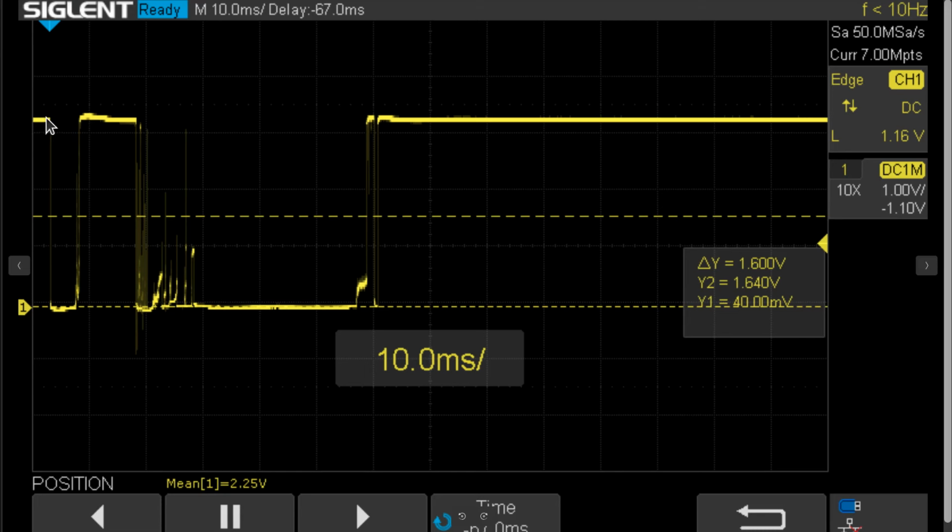So in this case, it would go from a 1 to a 0, and as long as it stays 0 for max count number of clock ticks, and remember, I'm running at 25 megahertz. That's not a very long time given this scale, but for testing, we don't want to have several million clock cycles. It would take 4 hours to run the simulation and be difficult to plot. All right, I'm just saying.